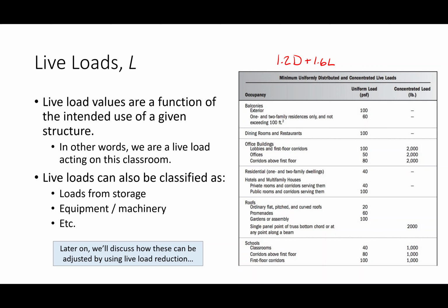Because the live loads are less predictable. That's exactly right. It's 100% right. We are more uncertain with live loads than we are with dead loads. I can probably predict the dead loads on an element with much more accuracy than I can predict how heavy the sum total of students in a classroom are on a beam, right? So we up the live load factor a little bit to account for that uncertainty. That's where LRFD comes in. It handles those uncertainties differently, okay?